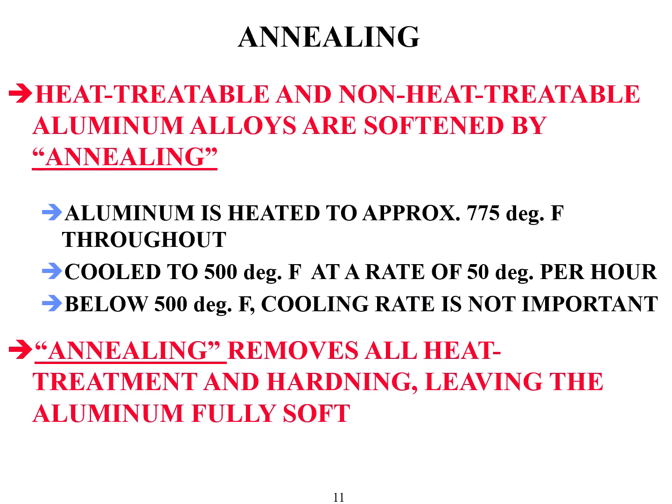Annealing in any material is the process of softening the material. And once again, that's a desirable characteristic in some pieces because if we need to make a complex shape, if the material's hard, often it'll crack before we can accomplish the shape. So you do see where annealed materials would be necessary. Now, once the annealing's done, it's fully soft.